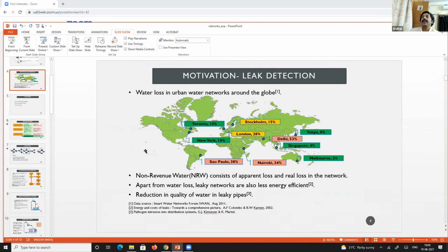As I mentioned, leaks result in sewage entering the pipelines. So if you're able to isolate the leaks, then you can cut down the problem of sewage entry. If the question is whether you can detect sewage entry, then if you have some concentration measurements or quality samples, we'll have to see how to bring that information in to determine where the leak is.